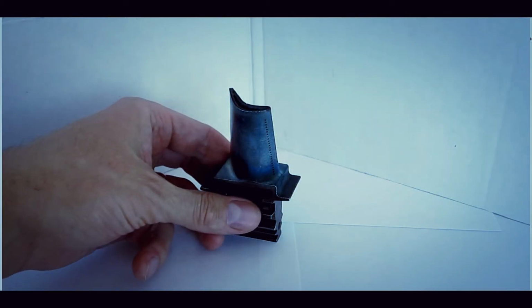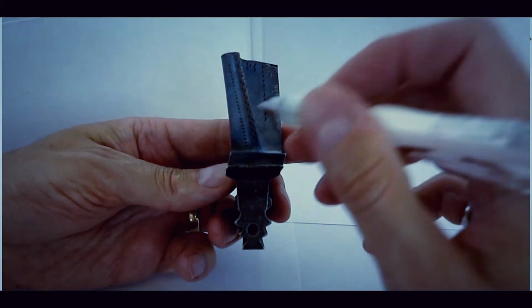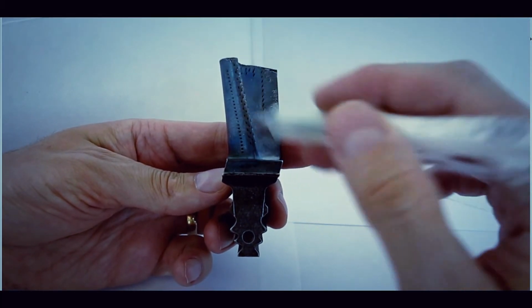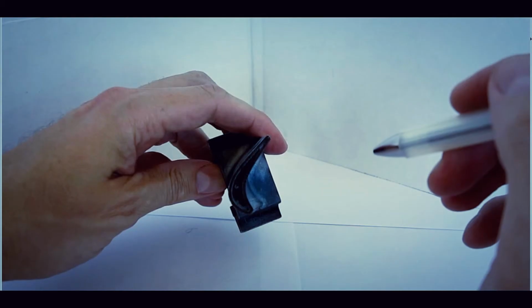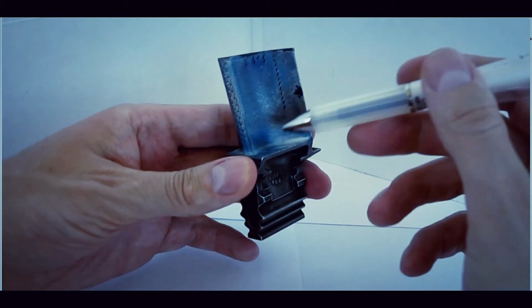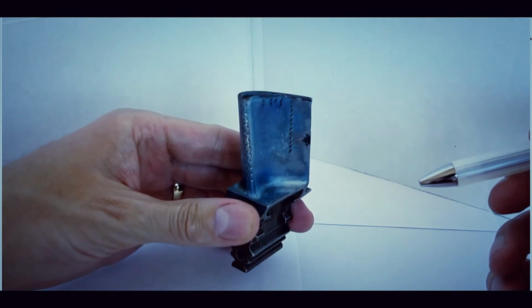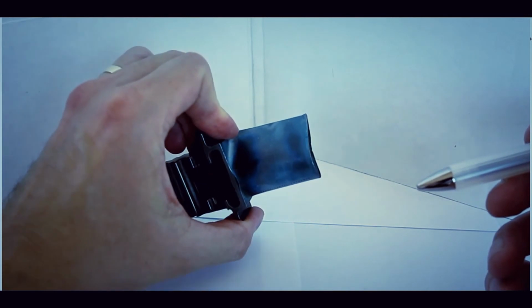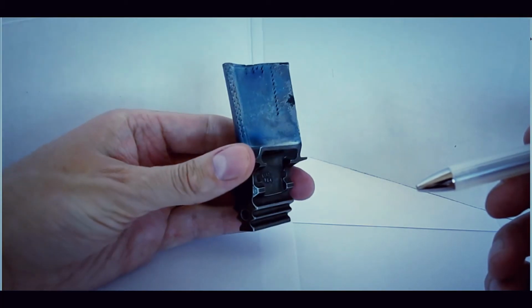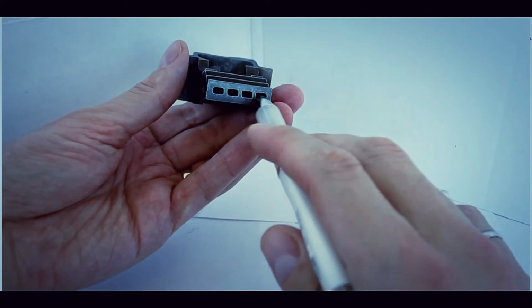This is the blade from a gas turbine engine, and what you're looking at here, this is the leading edge of the gas turbine blade. Looking at it from the end, you can see the cross section, and so it's a very curved shape. The other thing to notice, there is a bit of a bluish white coating, and that would be a coating to protect it from the high temperatures that would be encountered within the exhaust gas stream of the gas turbine engine.